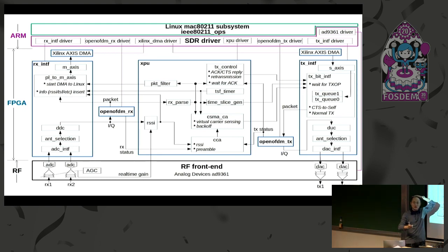You should do a packet filter for Linux, otherwise the workload of Linux is too much. Here we also need to handle all the DMA stuff, RX DMA. From FPGA to Linux, we set up ring buffer DMA, actually keep running in the background. In the driver, we check the DMA status. That's why we know what's the latest packet.